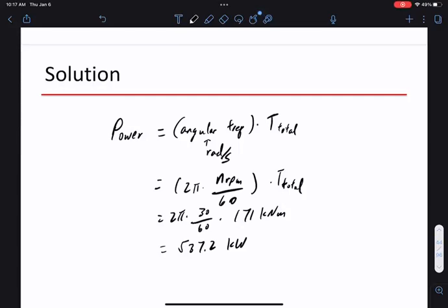So if you build a 2-bladed turbine, the turbine wobbles back and forth. Because vertical is one weight distribution, horizontal is another weight distribution. So you see this kind of wobbling. And if you build a blade very big, the mechanical stress from this wobbling becomes too much. Okay, so 3 is sort of a good trade-off.